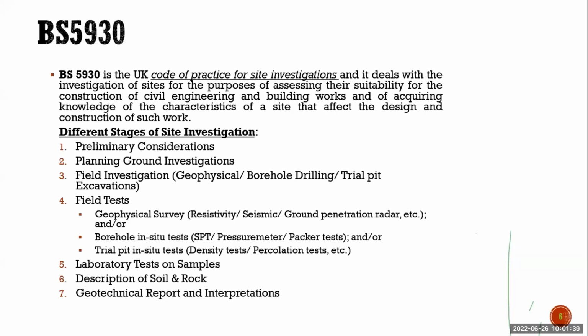First, we will do the preliminary survey. After the reconnaissance survey, we spread the boreholes. Then we see, is there any big variation? If there is any big variation, in the detailed survey we will have many boreholes. And if there is no big variation, we will keep minimal boreholes in the detailed investigation with some chemical test if it is required. Okay, so this kind of information we can get in the detailed investigation. These are three main stages in site investigation, whichever standard you follow.